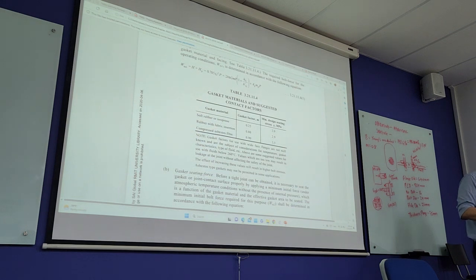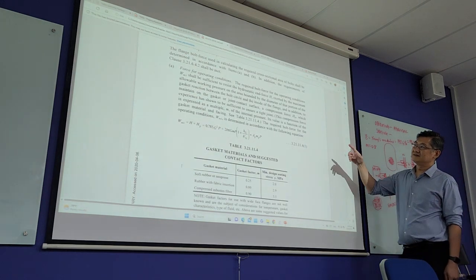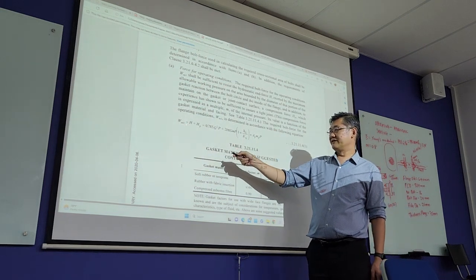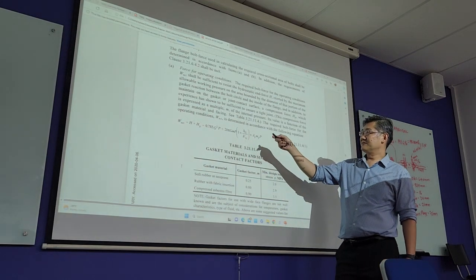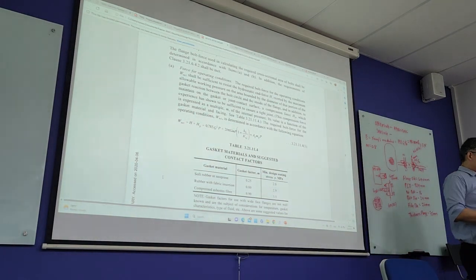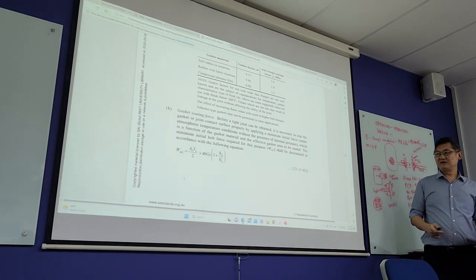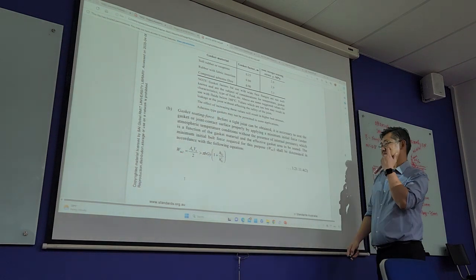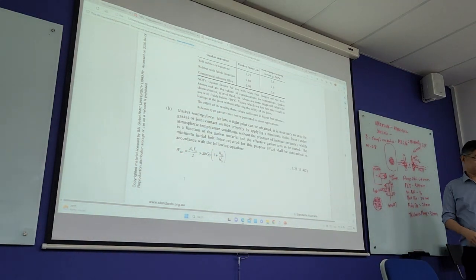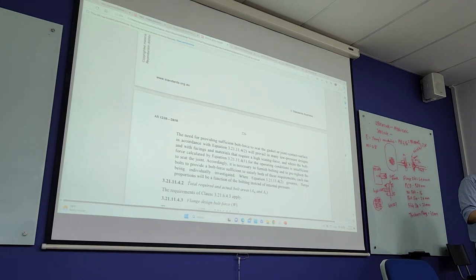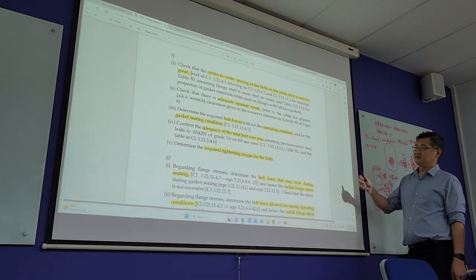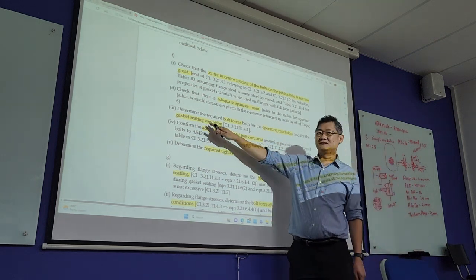Okay, so you need to identify: for operating, meaning with the hydrostatic, it is WM1. WM1 for operating. For non-operating or seating condition, it is WM2. Alright, so this is how you do this question, operating, seating.